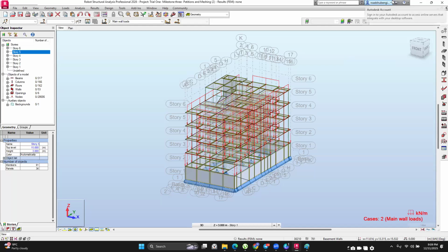We are going to start with approximating the weight of the water. So if it's a 10,000 liter tank, we divide that by 1,000 first so that we can get the volume in meters cubed. If you divide 10,000 by 1,000, you should get around 10 meters cubed.